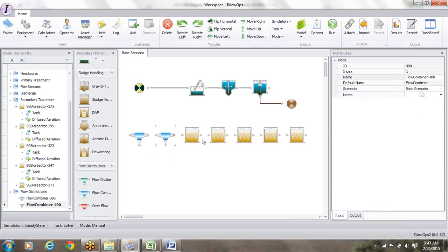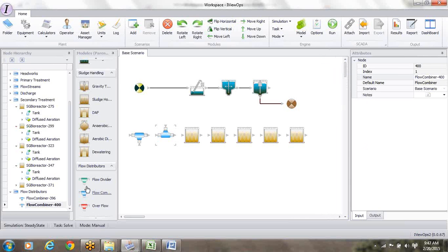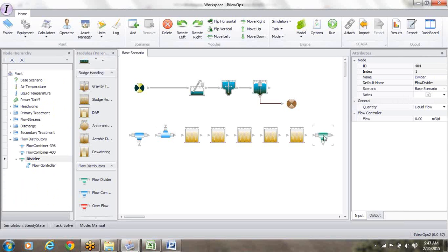Now I want to show my nitro recycle coming in over the top here. So it'll come in here, and I want to flip this and use the flip horizontal, and that has been flipped. Okay. Now the next part, if I just want to continue with this and then come back to the tanks, I know that the nitro recycle system is embedded within this flow divider.